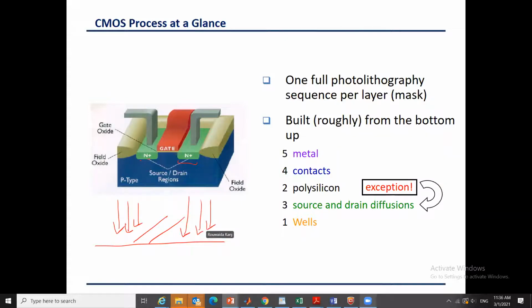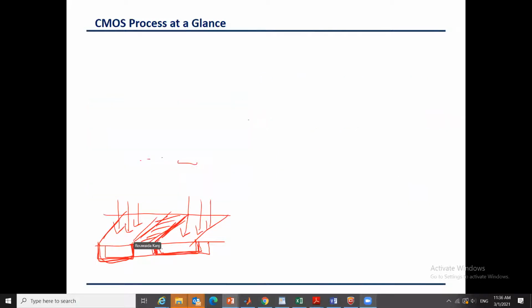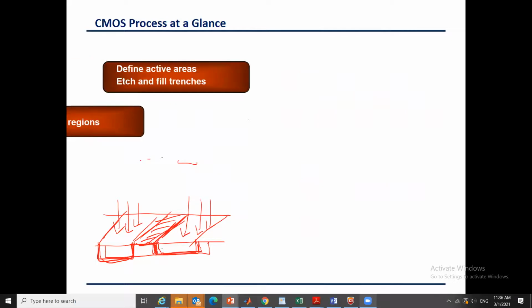And when they expose a non-rectangle around the gate, if this is covered, the drain and the source will build symmetrically around the gate. You see the gate is centered between the drain and the source. And by fabrication, they realized that it is more difficult to really center the gate afterwards. Okay, this is just a processing step, to know for your own information.